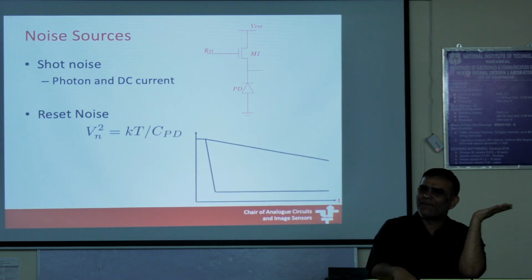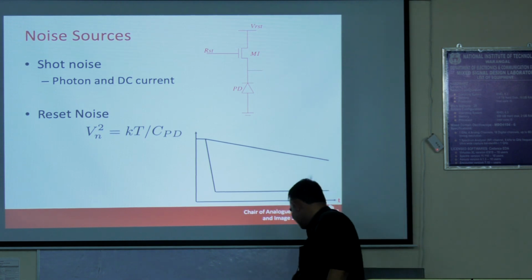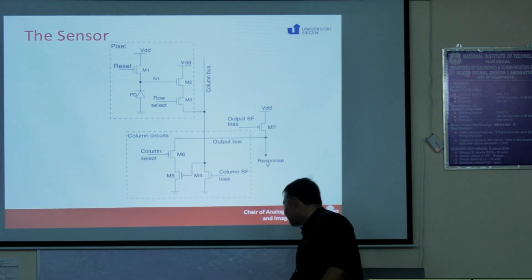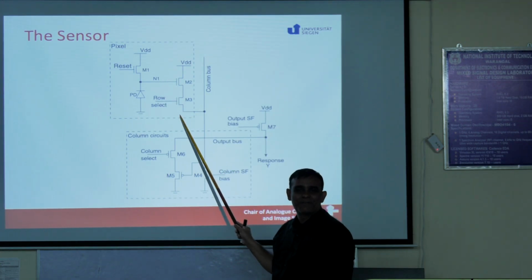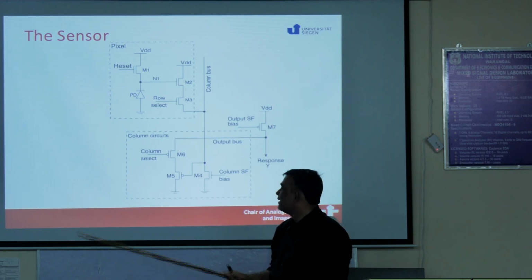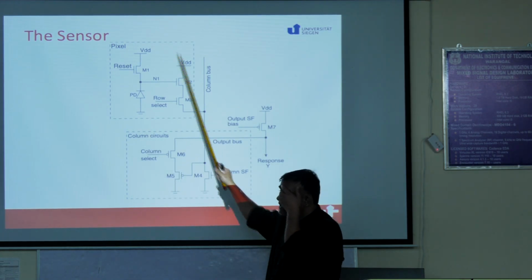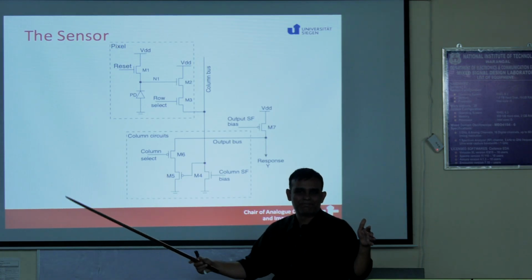But think of it this way. I've already told you, I need the smallest size transistor possible. So you can go in a technology, pick what is the smallest transistor you can make. Put 3 transistors together. Put the smallest transistors together in that configuration. Put in the largest diode which you can draw. I mean, you at least have to think how big your pixel has to be.